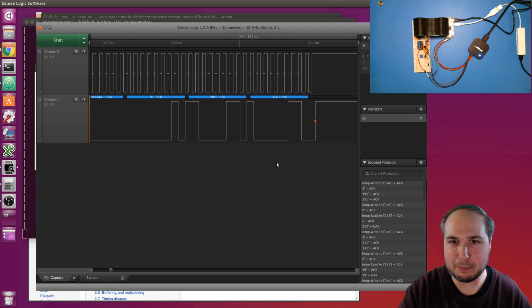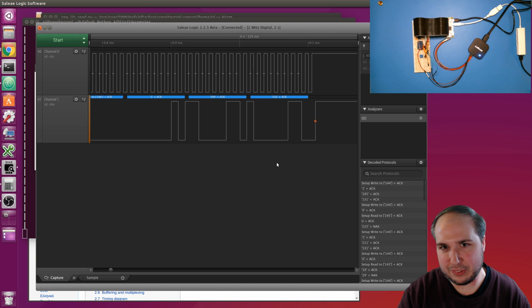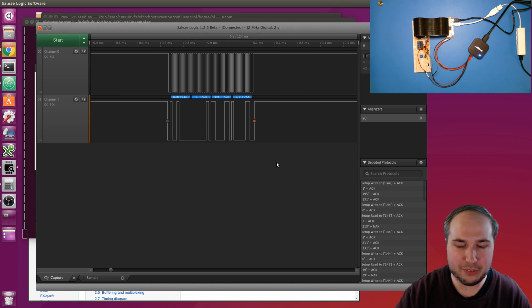So my Python script has to tell the ADC what gain and what sample rate it needs to use. It has to flip some bits to say, okay, do a single shot capture. But that's the first transaction here that we can see. We're doing a write to this device. We're specifying the register, and then we're specifying the value we want to write to that. So there's basically 3 bytes of data that we're writing to this device.